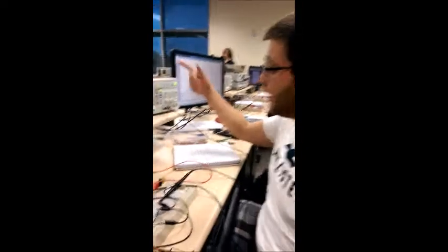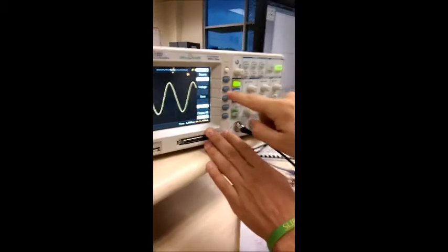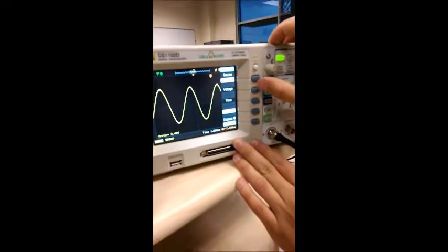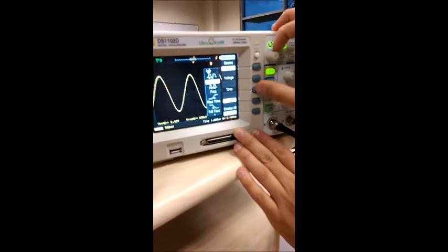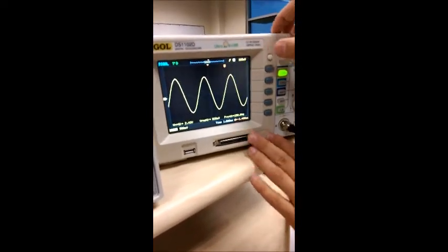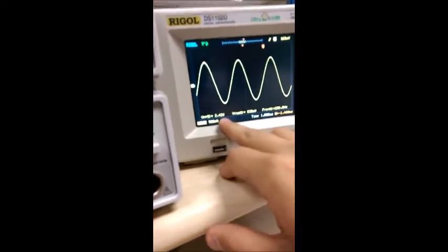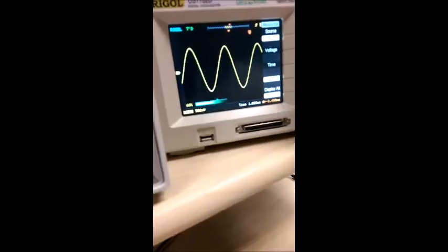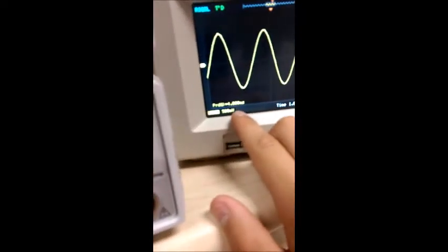Once I have built all my circuit across the R2 resistor, I'm going to the oscilloscope and click on measure and use voltage peak to peak, voltage VRMS, and time, the frequency. As you can see, the peak to peak is 2.4042 volts, the VRMS is 830 millivolts, and the frequency is 250. Voltage time period, my period is going to be 4 milliseconds.